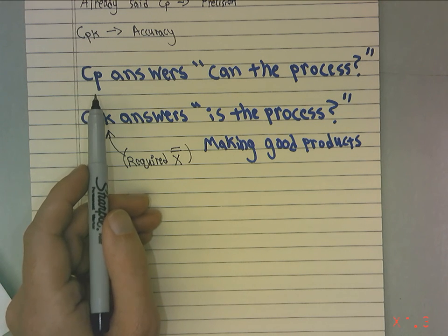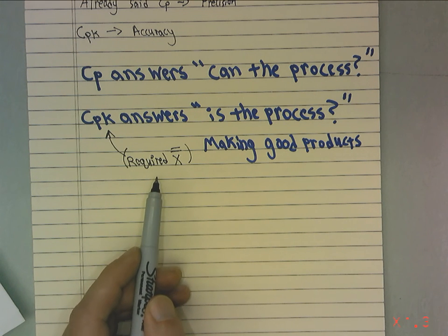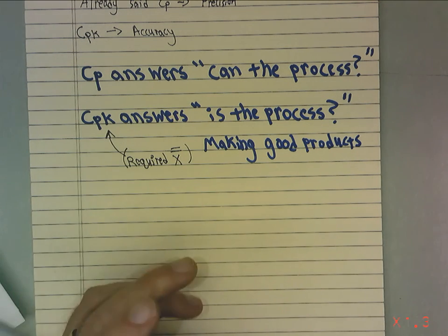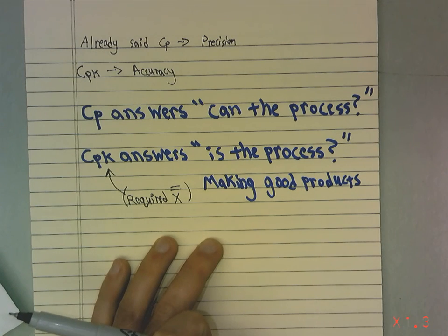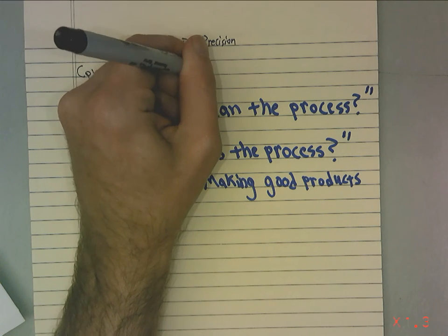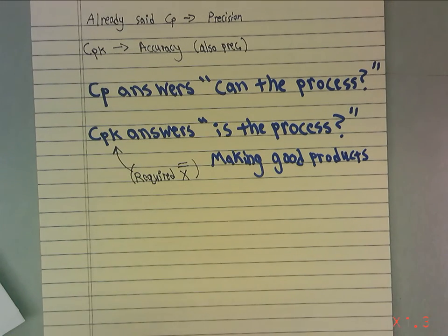Yes, we needed to have done previous production or have a good idea of the standard deviation for a process, but this requires us to actually be making the product and measuring it to get CPK. So, does CPK check for precision? Yes, it does, actually. So we use CP for product selection. We use CPK as the quality control check during the process.